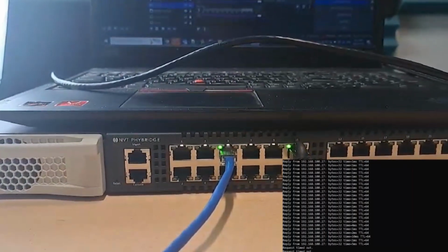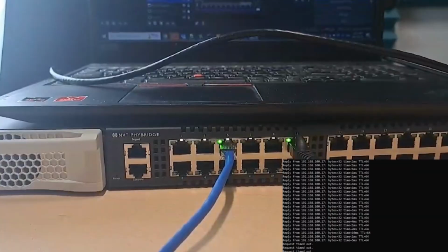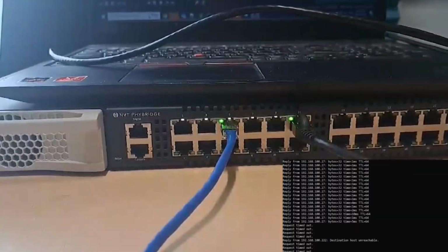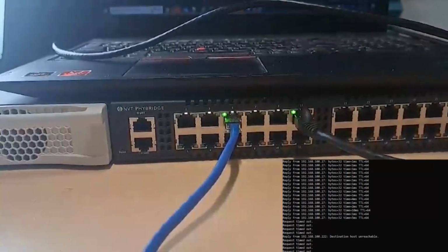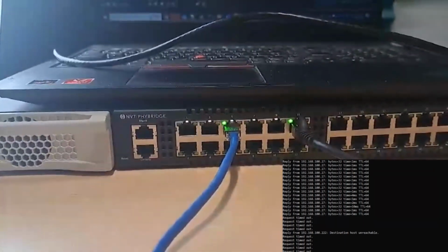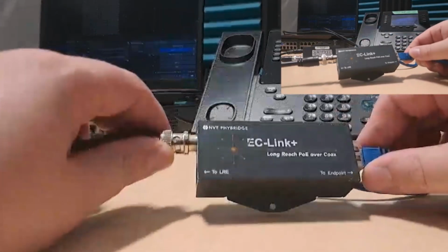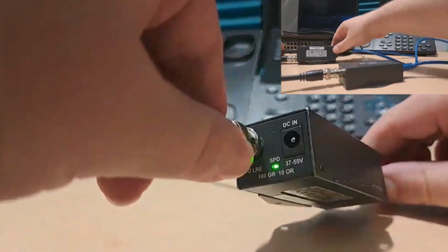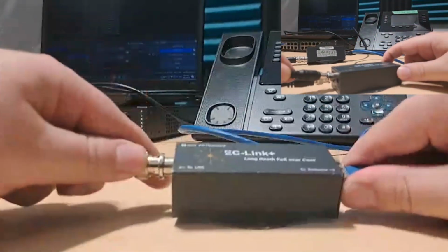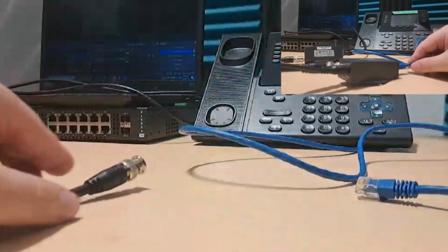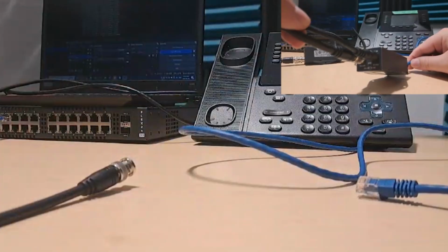It will usually take a minute for the endpoint to power up. In the meantime, we want to ensure all LEDs are present, indicating power and connectivity across the PoE port, and the LEDs on the adapter ports. If the issue persists, we can begin replacing the adapters to see if connectivity is restored. Be sure to test whether the adapters power on with a known working power supply. Don't rely solely on PoE. Always ensure that the adapters can power through both PoE and a local power supply.